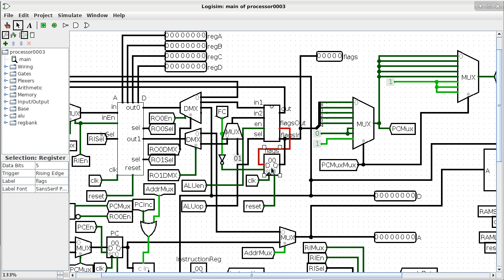Okay, good point. What's the piece just to the right of that, with 0, D, Q? That's a register. So this is where we left off from the last lecture on Tuesday. Remember on Tuesday, I said if you hook up 8 of those, level, edge sensitive, resettable, clocked D flip-flops, and they all share the same control lines, but they do not share the actual data line. That's how we look at it from the outside. The D port is the input into the whole thing, so it is 8-bit wide. Q is the output, also 8-bit wide. EN is the level sensitive enable. This little triangle is the clock; that's where we hook up the clock line. And the last one, which has a 0, is our clear, which is the reset line. That's basically what we talked about on Tuesday.